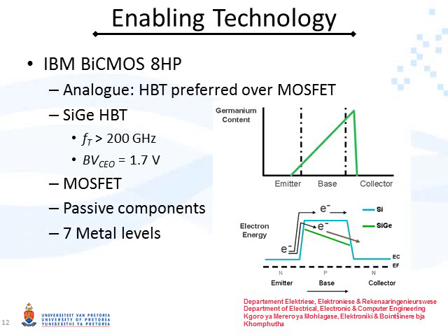The requirements to integrate analog and digital circuits and extend the capabilities of the same power amplifier chip have become very important. Owing to higher gains and current densities required at microwave and millimeter wave frequencies, bipolar devices have been the preferred choice at higher frequencies. Previously, gallium arsenide based technology was the preferred choice. However, recent advancements in silicon germanium HBT technology, especially in terms of reduced manufacturing costs and power consumption, have made this technology favorable at these frequencies.